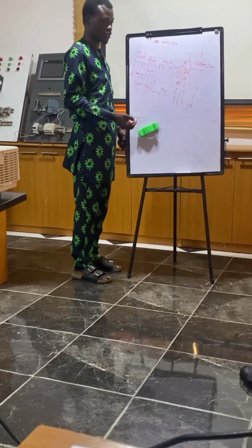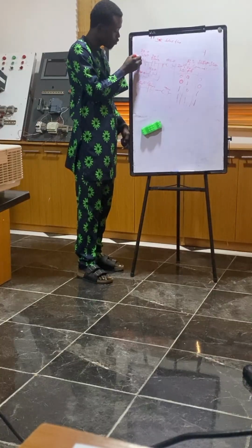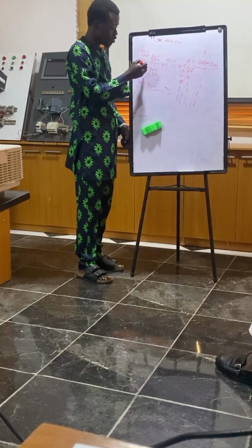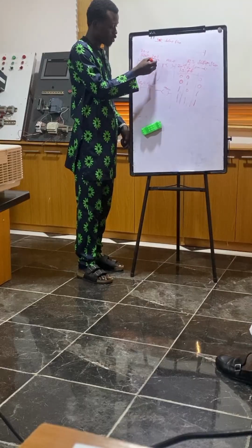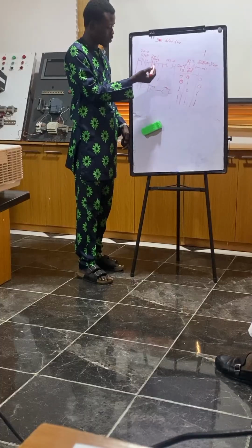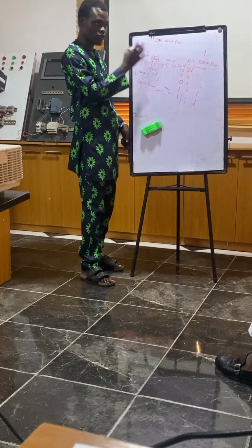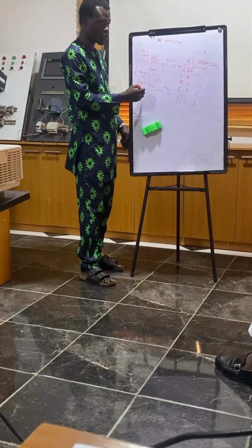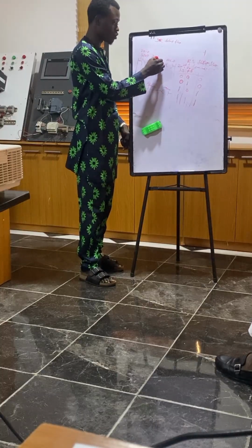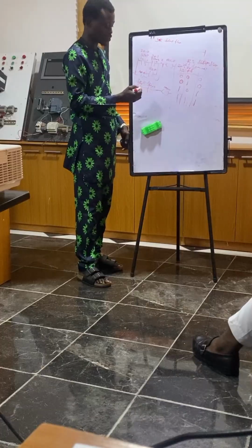So what will be the case? Now let's test it on our truth table. When the two of them are not pressed, there is a signal state of 0 here, 0 here. So there's an inversion. This is 1, and this still remains 0. 1 and 0 will not agree. But as you are doing that, you need to confirm on this end as well. So at this point, you know that your RLO will be 0. Okay, so let's see what this bypass will do for us.